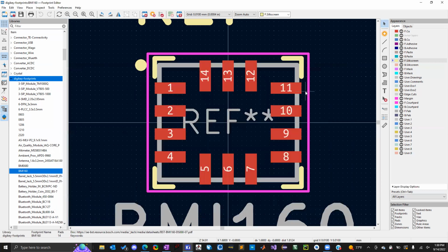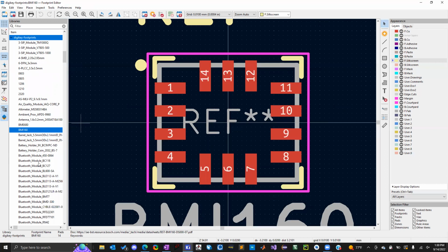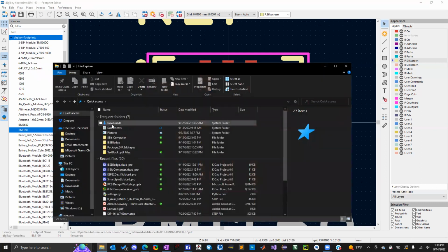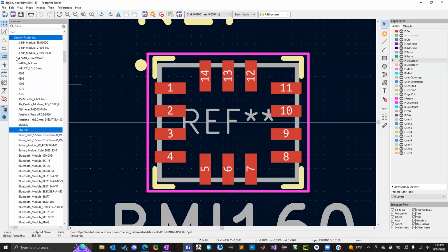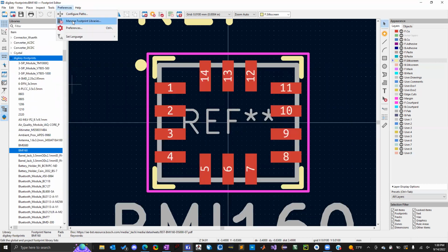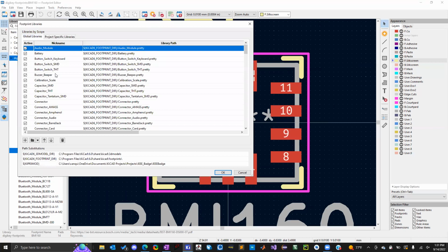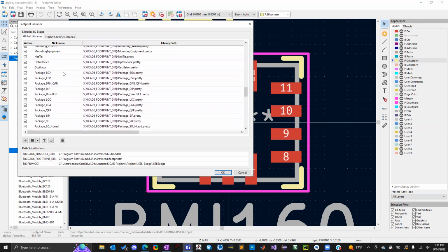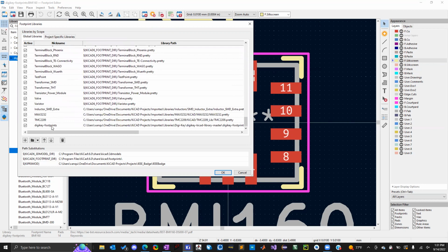I wonder if it's an issue with how I have it set up, because there were some weird changes. They changed a lot of stuff when they went from KiCad 5.0 to 6.0. Well, no, it's up to date, but I had 5.0, so some things are a little weird as far as where things are located. I wonder if my libraries are supposed to be elsewhere. But if they're in here in the global libraries, then you should be okay.